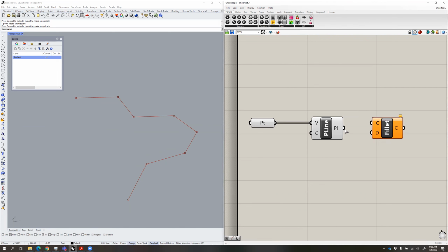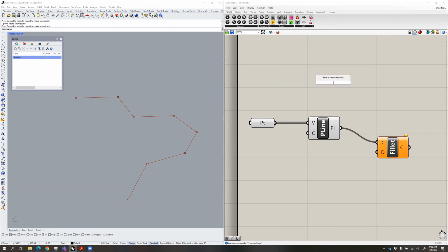Okay, so I'm going to take this line here and plug it into the curve to fillet. And then you need to add a distance. Basically it's going to measure a distance from that point of the line, and it's going to fillet that curve to that distance. So I'm going to add in a number slider. Let's do 20.0. That adds a number slider like so that you can get a number there. And then let's add that there. So see what happens now. This number slider takes that curve and begins to soften the edge. It fillets the edge of it.